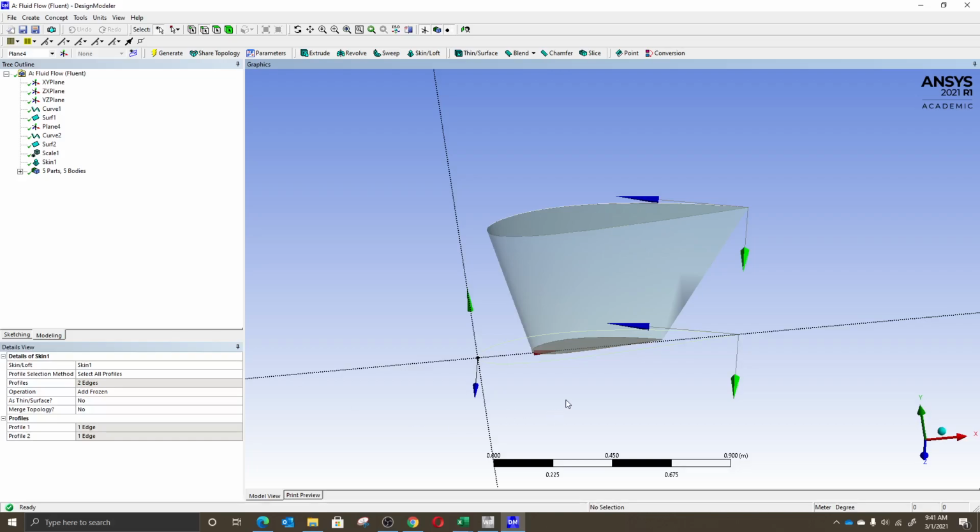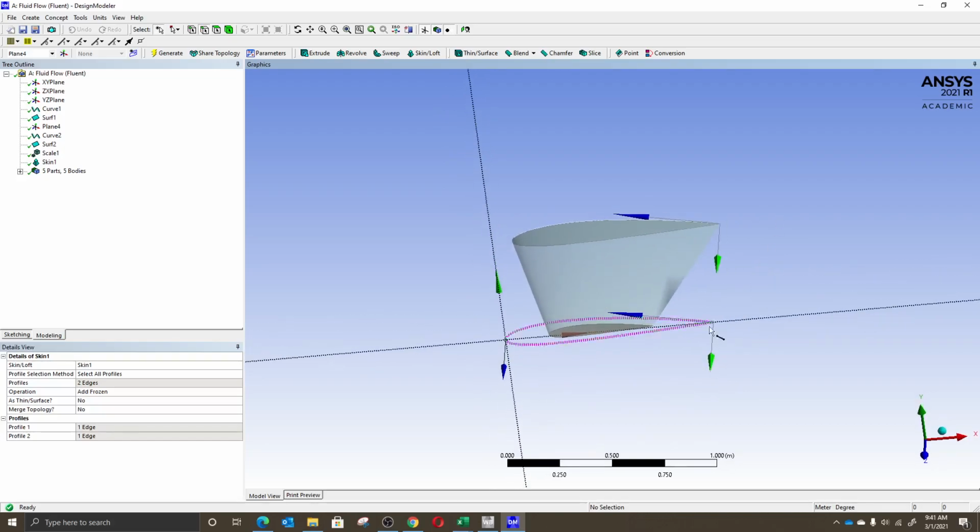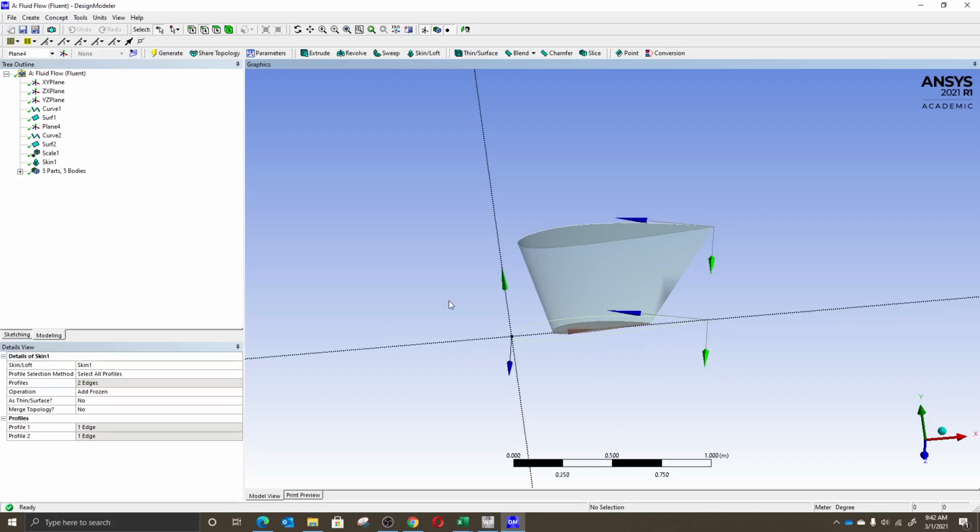There are a couple of people, or maybe just one project, who is going to analyze flaps, right? For flaps, you essentially have to import a new airfoil, make it smaller, and then transform it, translate it to another location, for example a location here on top, and create different geometries. If you had any problem creating the two separate geometries, please make sure to contact me and we'll go over them. So we have the wing, but we don't have the air surrounding the wing.